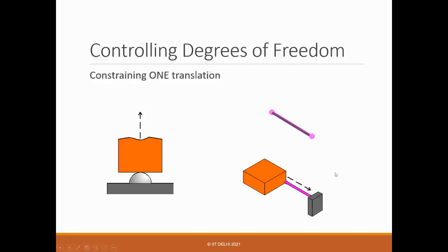And of course, when we clamp it, suppose we remove the articulating joints and rigidly clamp it to the body, then we understand that this member is no more a truss member, it's like a beam element. So a beam element and uniaxial, right? So it's a slender rod, which can bend and can get twisted.